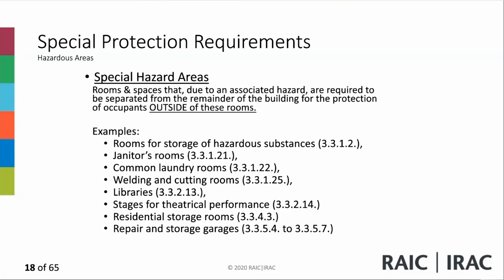There are provisions for dispensing of fuel under 3.3.5.8. Facilities for dispensing fuel having a flash point below 37.8°C shall not be installed in any building, except that this requirement does not apply to a canopy which is open for not less than 75% of the perimeter. Otherwise, facilities for the dispensing of fuel having a flash point below 37.8°C shall not be installed above any space intended for occupancies. And then we have 3.3.5.9 for multiple tenant storage warehouses, except as provided in sentence 3.9.3.15.